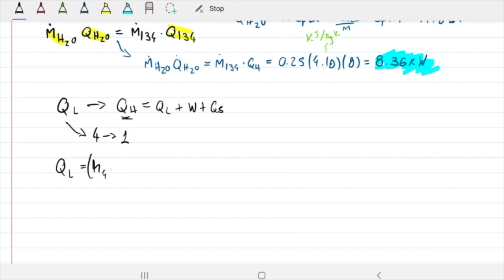So let's start by doing the normal, straightforward way. Going from 4 to 1 times the mass flow rate of refrigerant. We have all that information. That is about 5.404, and it keeps going 449. So let's just stop there. So it could be as easy as that, but we're going to have to calculate the work of the compressor to calculate the coefficient of performance anyway. So we could have done the other way around.